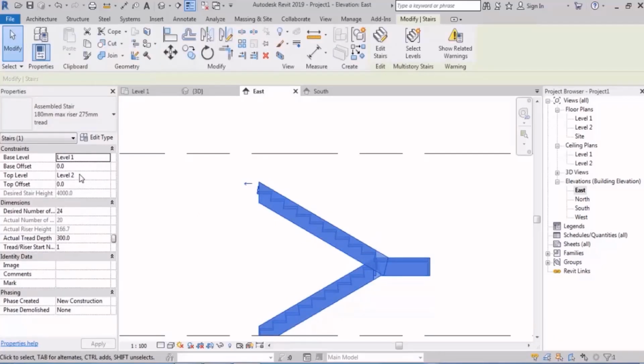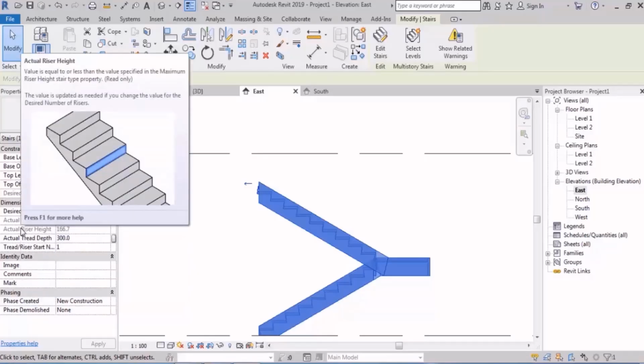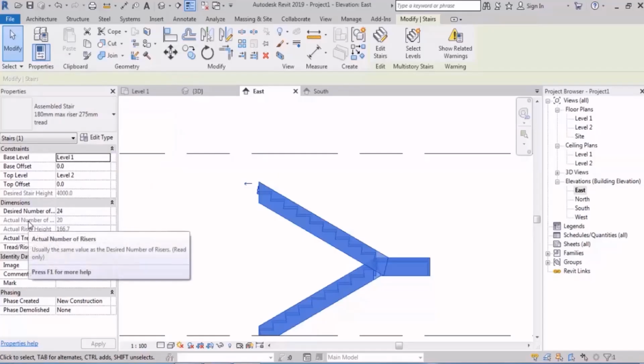Now, what is it? Well, look and pay attention. When you edit this boundary, Revit only cares about the place of connection only here. So if you want to draw that arc, if you keep a piece of this connection, right? You saw I clicked on that unjoin?